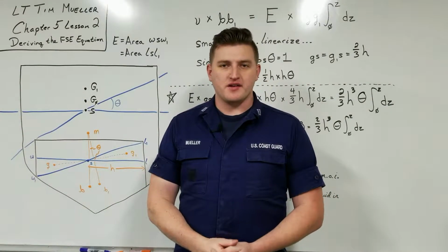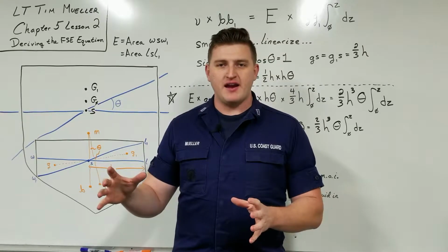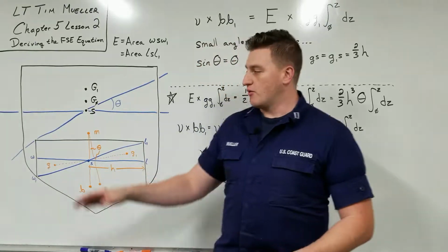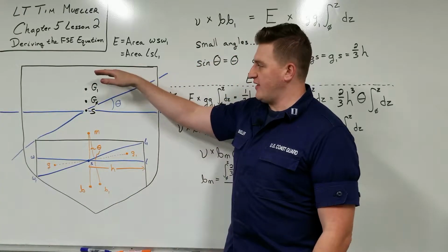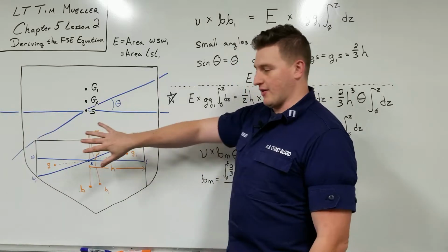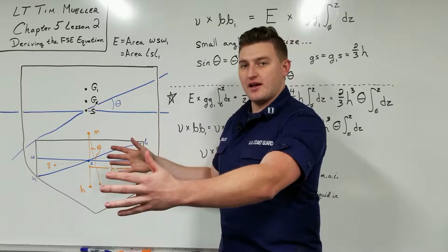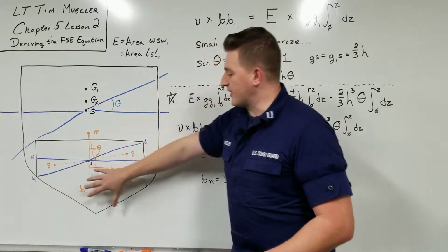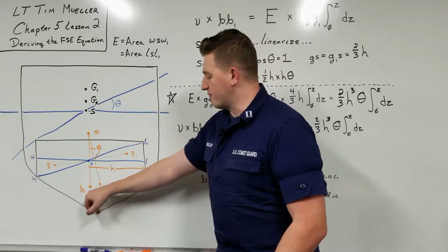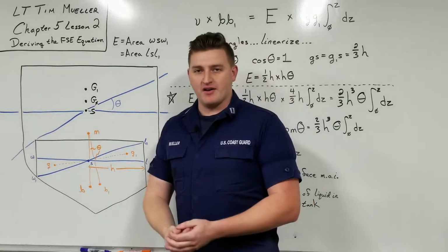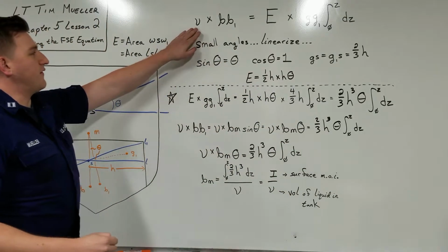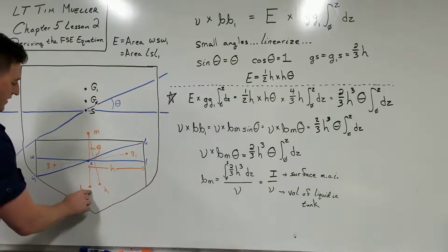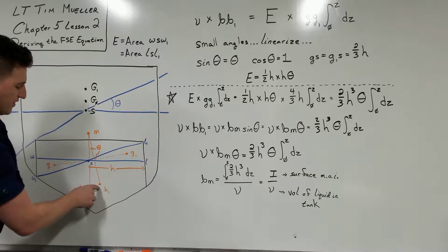All right, so first things first, we have to start seeing the moment that's created by the movement of all this liquid. Remember, this is an actual tank, so it's in 3 dimensions. We have a 2-dimensional transverse perspective here, but also imagine it coming out or going into the board. It has some sort of a longitudinal length. So we have to find how much is this moment from the contents going from here to here. So it goes from B to B1. You have to take that volume that we have inside the tank and multiply it by the distance B1. So all this content is essentially going from this center of gravity to this center of gravity.